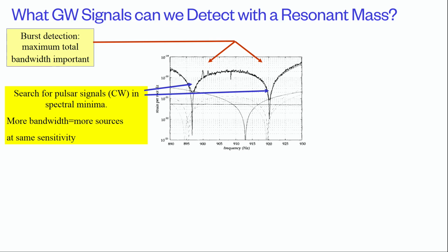Does that make sense? That makes a lot of sense, right? So which basically means that for me to fully understand that plot, you would also need to pass me the information on how long you've averaged, right? No, because when you measure a level of noise, it's averaging to a certain value. Right, but I need to know for how long you've averaged. No. What we need to tell you is the frequency resolution of this measurement. And if you know the frequency resolution of the measurement, then you can convert this to strain.